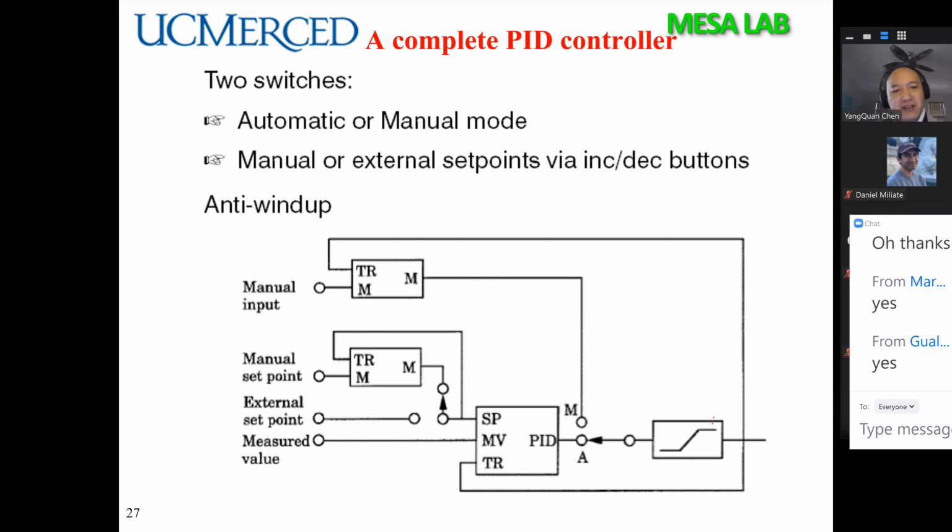Basically, you have a saturator, you have an actuator, and in the end you have a plant in here. We are not drawing the other parts. We just want you to see you have a PID output in here. This is your PID control output. This is the set point, your reference, SP is R. This is your measured variable, Y. And this is the saturated control signal.